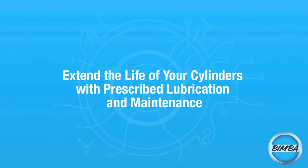Extend the life of your cylinders with prescribed lubrication and maintenance. Recently, cylinders permanently lubricated from the factory have become much more popular, lessening the importance of maintaining proper lubrication levels through the cylinder's life. However, for cylinders that require lubrication, one of the keys to maximizing the life of pneumatic cylinders is maintaining the proper lubrication levels. Cylinders that are not sufficiently lubricated can overheat, causing damage to components and degradation of seals. These tips will help you achieve maximum cylinder performance in any application you choose.